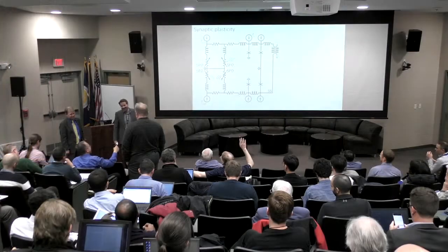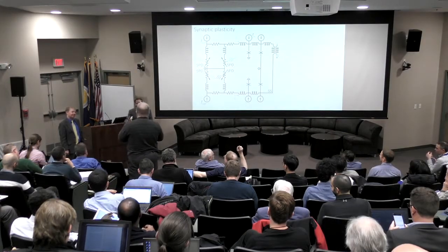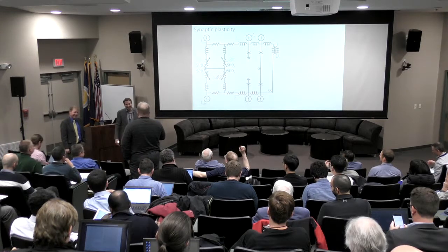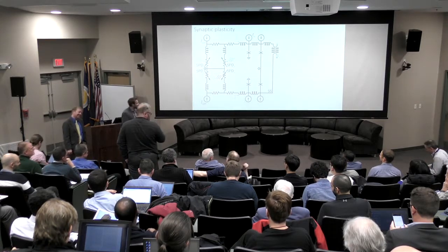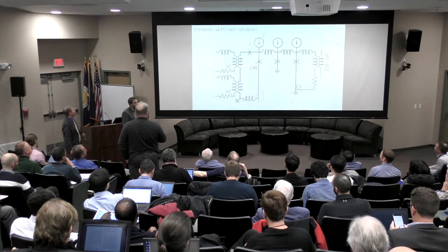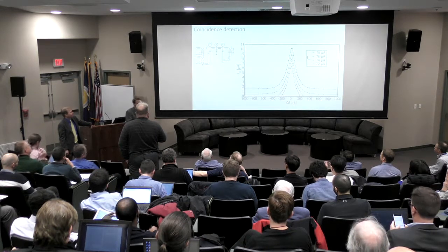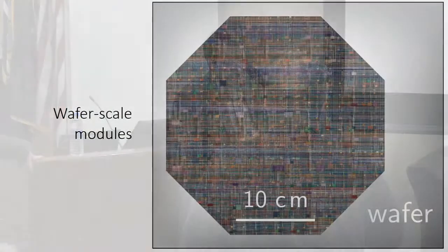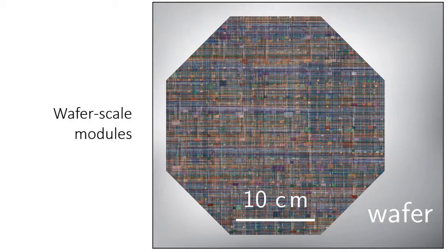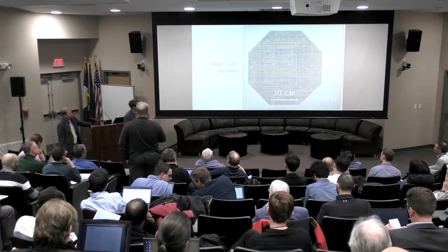Sounds great. It's not that bad. I really want the power and cooling question. Okay, so the power and cooling question is, first of all, cooling is manageable with liquid helium. You calculate the total power that's coming out of the wafer here. The wafer is dissipating about a watt if it's going up to something like 100 megahertz and down to 100 hertz, power law distributed across that. So a watt is very easy to remove from this surface area with liquid helium.